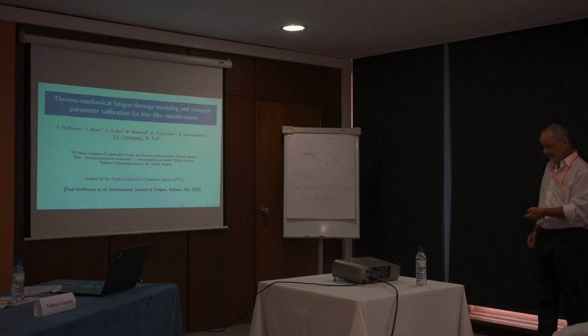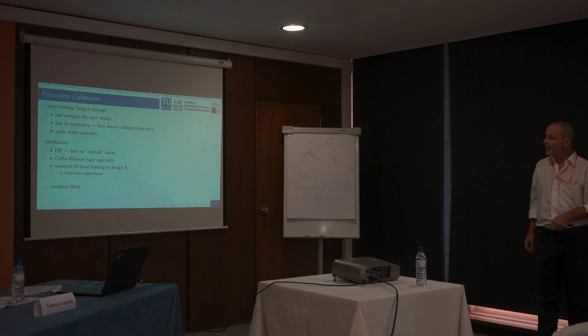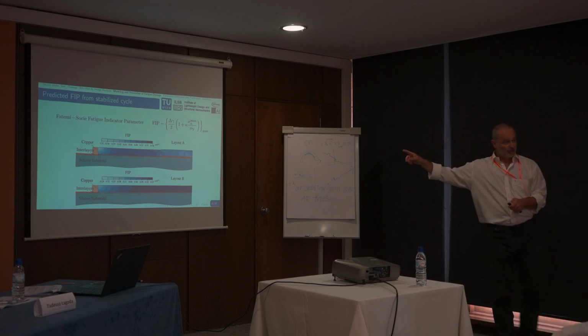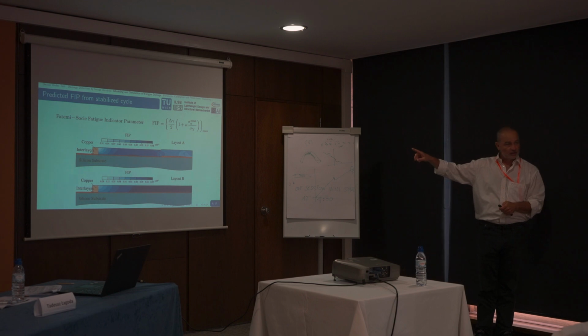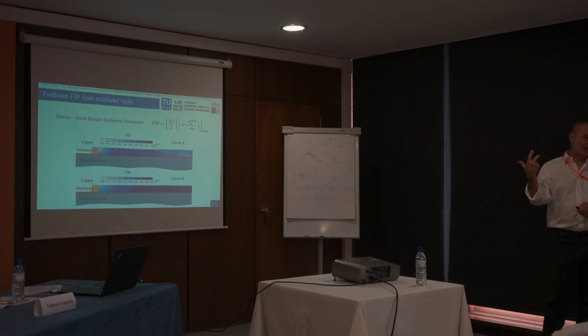And the fatigue indicator parameter is computed in every element. So we have here something like 20, 30 elements in the thickness. And for every element we compute this fatigue indicator parameter. On top I have to say the fatigue indicator parameter is based on triaxial strain tensors.